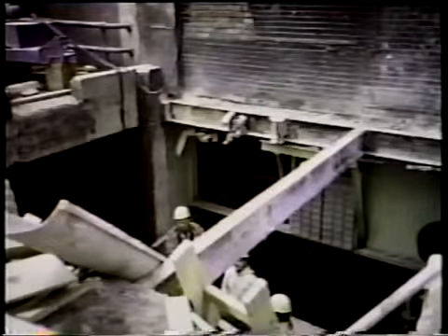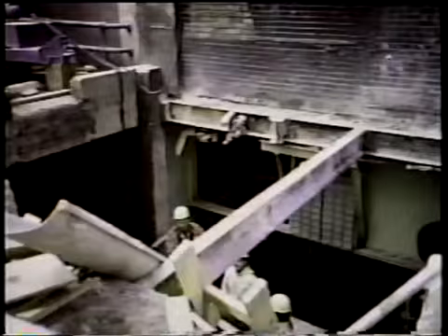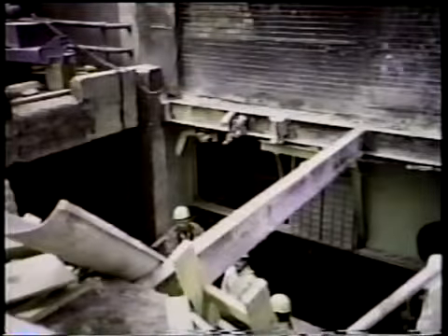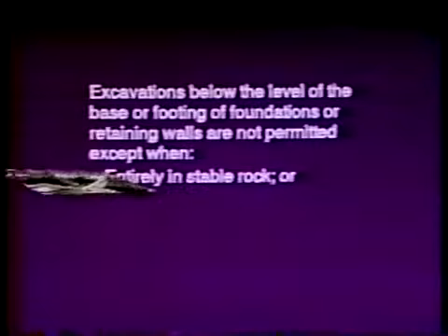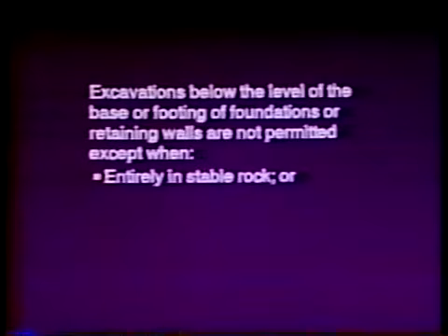Workers may also face hazards where the stability of adjacent buildings, walls, or other structures is endangered by excavation operations. Support systems such as shoring, bracing, or underpinning must be provided to ensure the stability of such structures for the protection of employees.